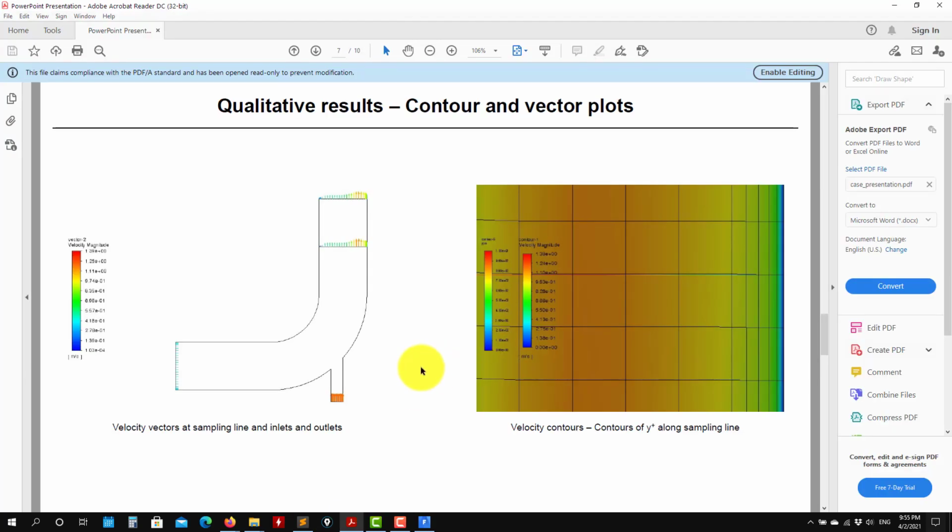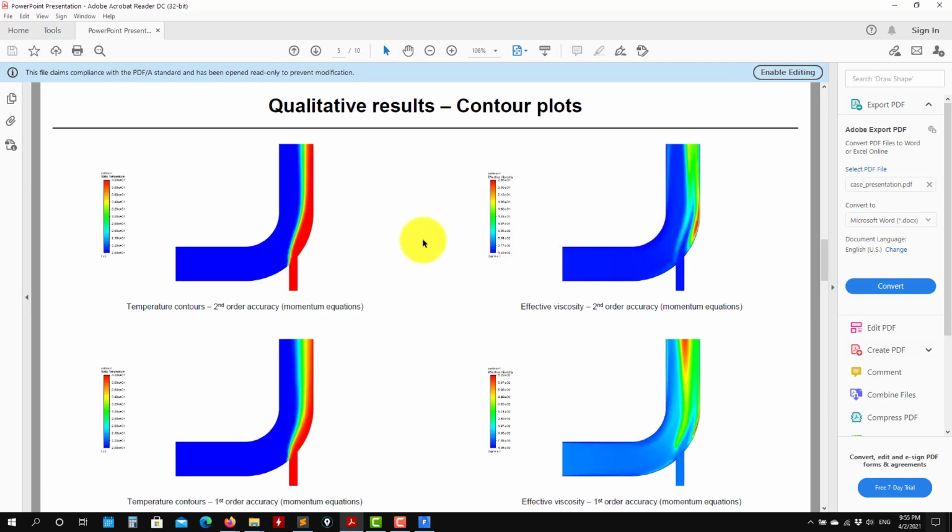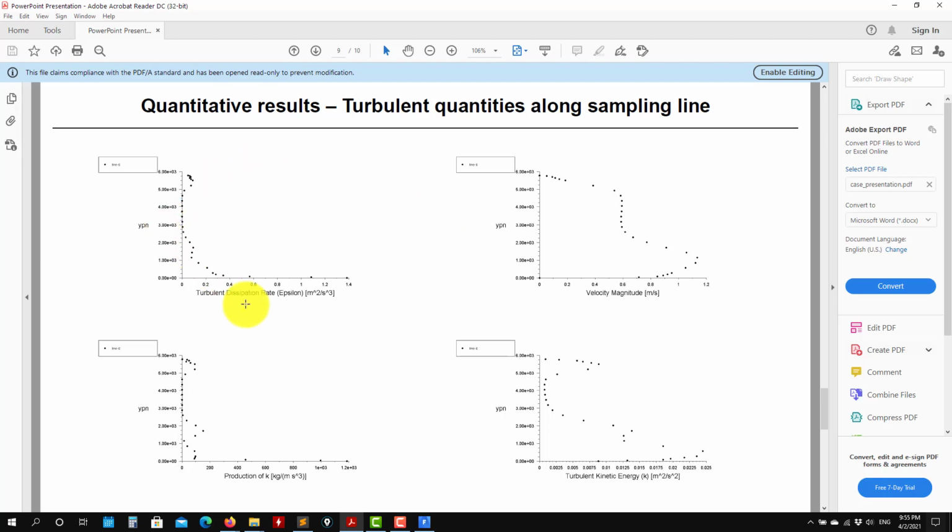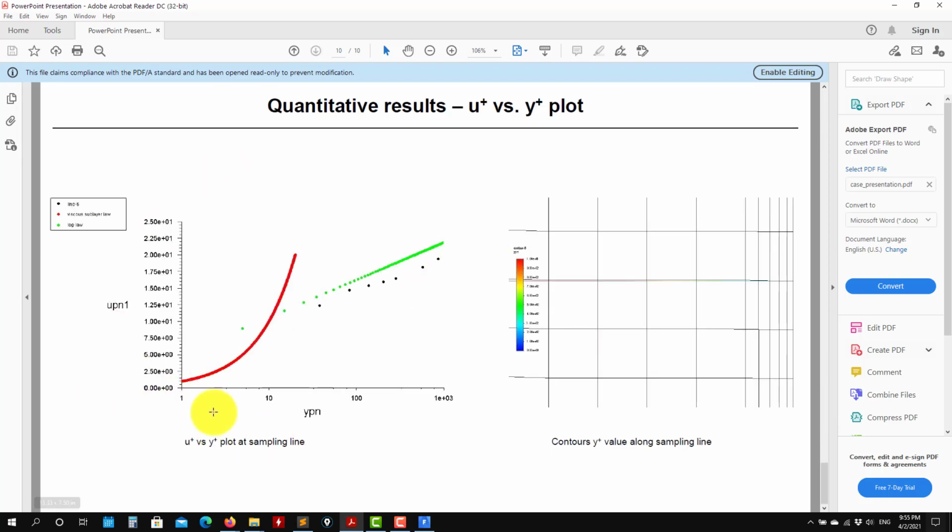So basically this was the advanced plotting. Try to reproduce these plots, and you have the solution there. As you see, this is very standard. It doesn't matter the geometry, you should always be able to reproduce it and be very critical. Sometimes you can get strange conditions and you may say, oh, but I'm not reproducing my profile. Remember, you can have many flows entering, interaction with the top wall, or separation, which is not recommended. So be careful, and look at where you are sampling, what the flow conditions are, and what is happening there.